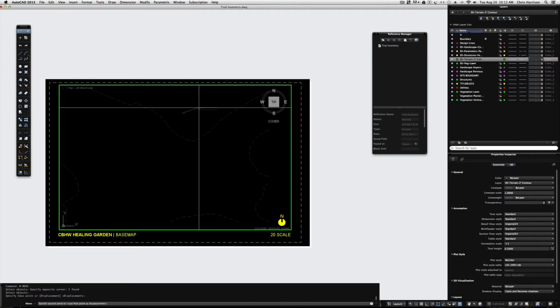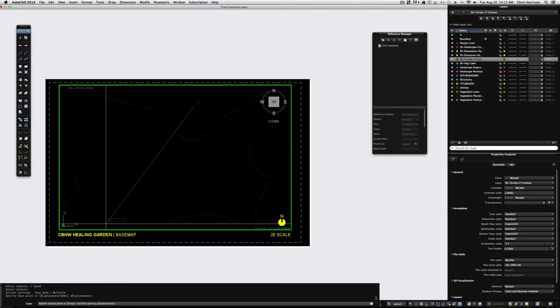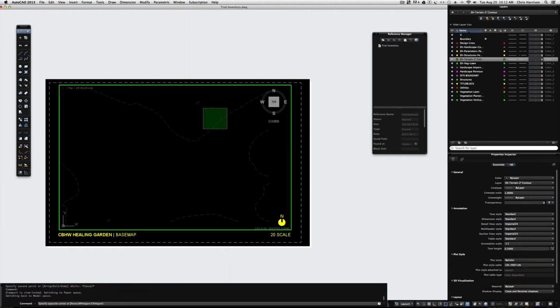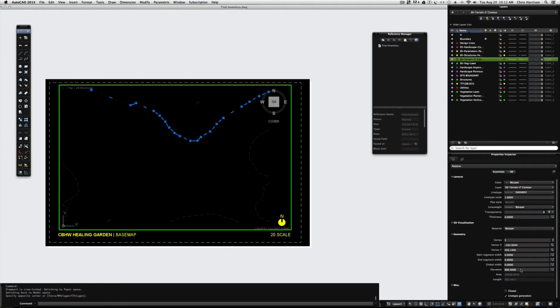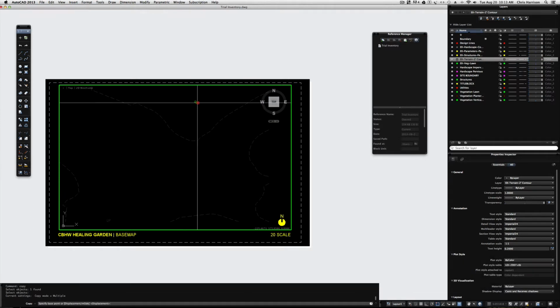So I'll call this like a low point over here. Just so we kind of have a visual indication of what's going on with the site. You could also tag that. I forget what the contour. I should know that though. So the elevation's 806. They could actually add an 806 to that as well. Because it's falling down, right?